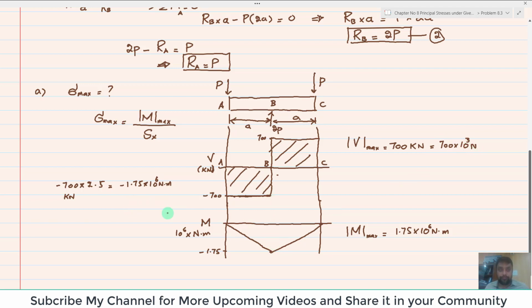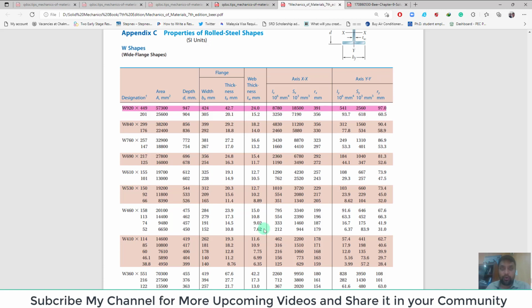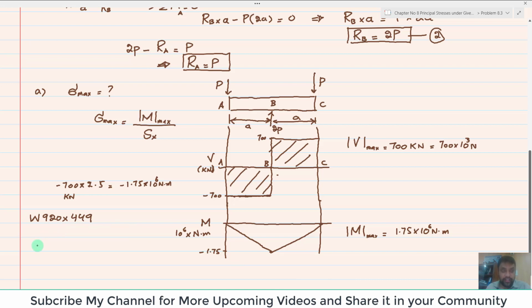Now we will move toward finding the section modulus, and as it is given that this is beam W920 by 449 rolled steel, if you go to Appendix C of the book of Mechanics of Materials, you have to take all the properties: depth of the beam, breadth of the flange, thickness of the flange, thickness of the web, second moment of inertia, section modulus. So you will note them and write them again. I have written their values.